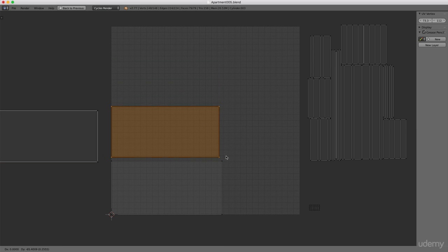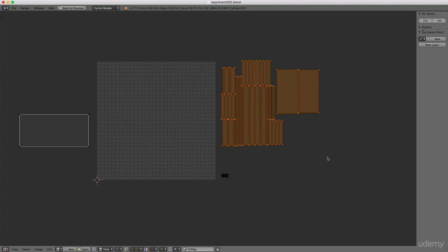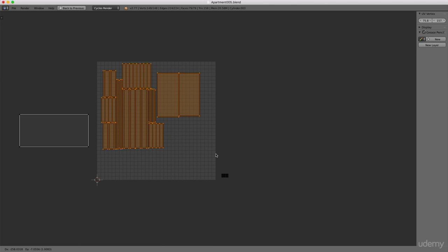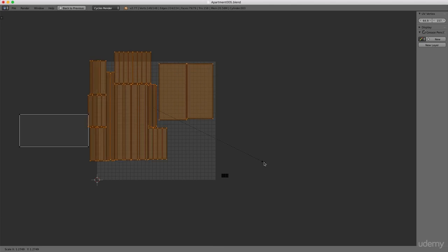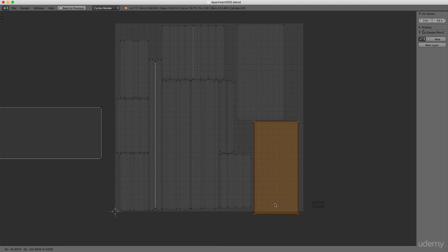And these pieces here are the underside and the top of the coffee table, but they're really not going to be seen very much at all. So I'm going to shrink these down quite a bit and rotate them 90 degrees, and I'll put them with all of these. I'll select the B key and click and drag to select all of these. And let's see how this works. I'm going to scale these up some and try and maximize the resolution within this 0 to 1 space. Let me try and put these in place in here.